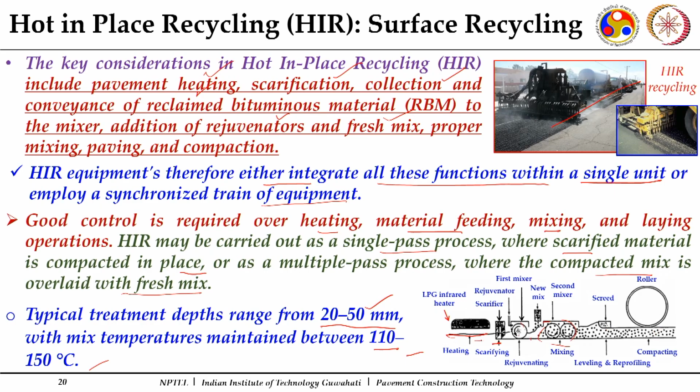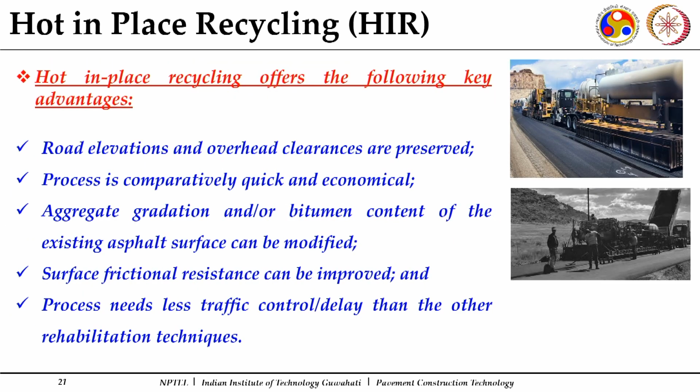So initially what thickness you have milled and what final thickness you have, which is later compacted. This is the benefit of hot in place recycling, because all this process is done in situ itself. Hot in place recycling offers the following key advantages. Road elevations and overhead clearances are preserved, because the thickness doesn't get increased, only a small variation may be there depending upon the materials which were falling short.